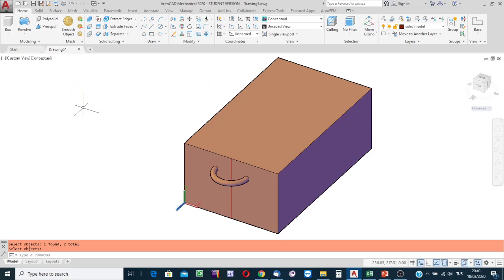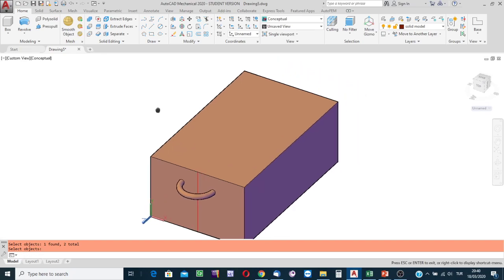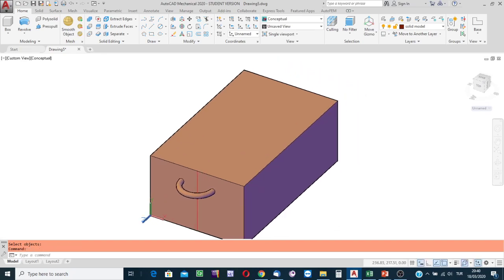And then in the construction layer, I'm going to create a plane. Why? Because the second revolve feature, in this example, has its symmetric cross section at the symmetry cross section of the rectangular prism. In other words, the plane of symmetry of the rectangular prism and the plane of symmetry of the second revolve feature coincide; their symmetric cross sections are in the same plane.